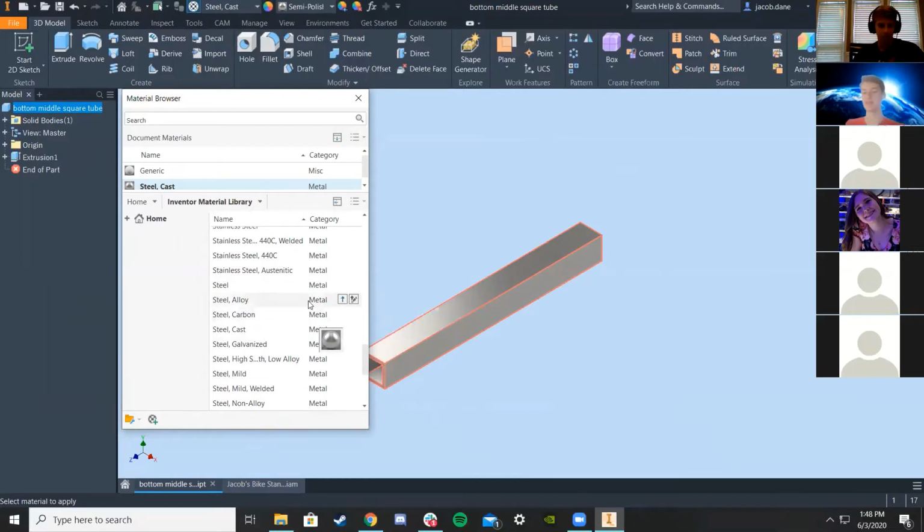Jonathan did say that it makes it look better, which I definitely agree with. Also, when we're making a robot, which we might try to do this year, if you define the material of all the parts, Autodesk is smart enough to estimate how much each part will weigh. If you figure out the weight of all the parts, it'll calculate how much the entire assembly weighs. That's another reason it's useful to define the materials, because especially in FRC, the weight does matter a lot.